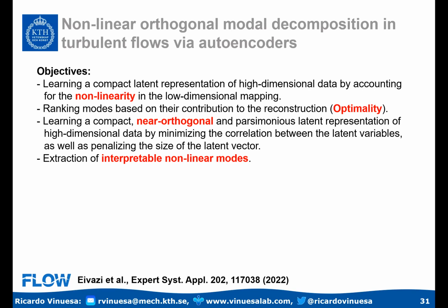That optimality is very interesting from the linear point of view. And the other interesting property of POD is that by construction, it gives us orthogonal modes, which means that they're going to be very interpretable from a physical point of view. The only problem of POD in principle is that when you apply it to turbulent flows, where you have nonlinearities and a very broad range of scales, you need many modes to be able to reconstruct significant fractions of the energy.